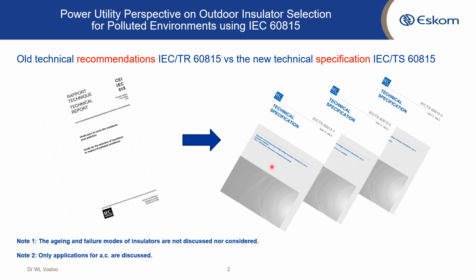Part 1 sets the scene. Part 2 is for ceramics, and Part 3 is basically for hydrophobicity transfer materials, or the new composite materials, and that's for AC. Unfortunately, we will not be covering the document for DC, and at the same time we won't be taking aging and failure modes into consideration, as this is not covered in the new IEC 60815.